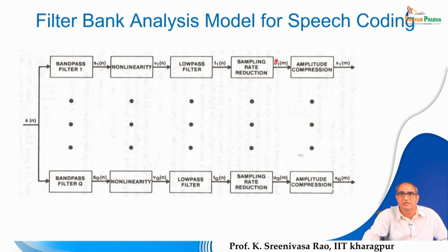So, for 1 second of speech, we are representing with 16 channels, where each channel is sampled at 50. That means each channel is represented by 50 samples per second, and with 16 channels, the total number of samples per second is 16 into 50, which is 800 samples. Now each sample is encoded by either 6 bits or 7 bits. Suppose we code with 6 bits, then we have 800 samples, each represented by 6 bits. So, 800 into 6 gives you 4800 bits.